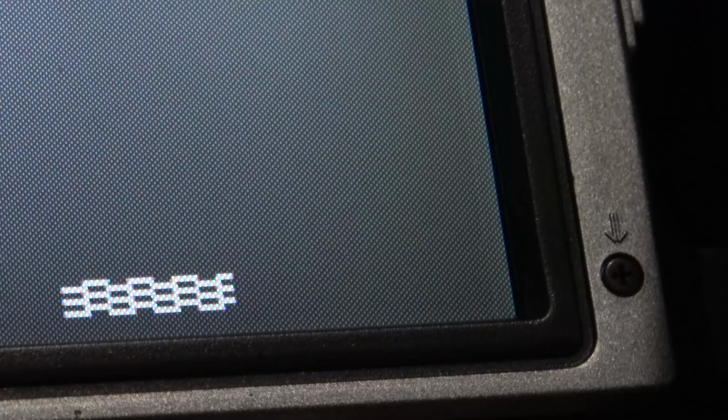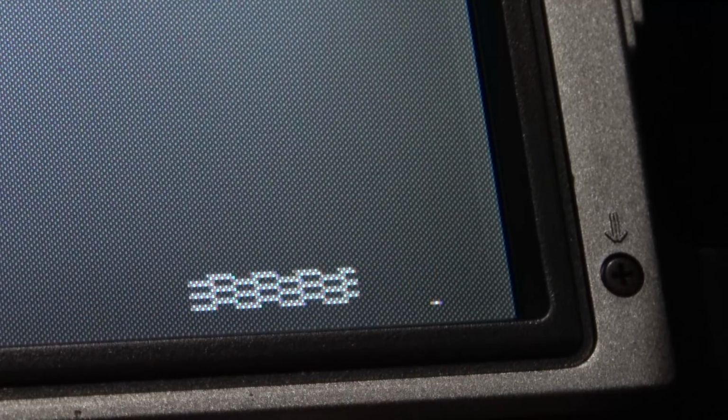So if we get too close to the edge, even if we don't get that close to the edge, we start messing up the sync. It's not even really a sprite routine. It's basically a software serial shift register routine. We could use this for other things like other sprites on the playfield, like if we wanted to make Space Invaders or something. I'm still not exactly sure what kind of game I want to make.